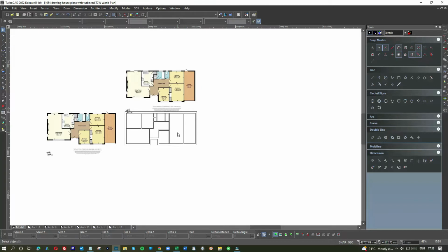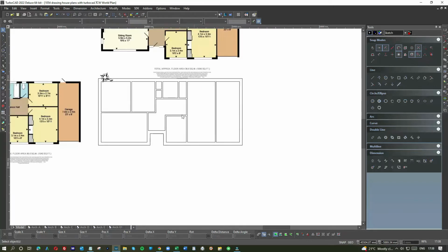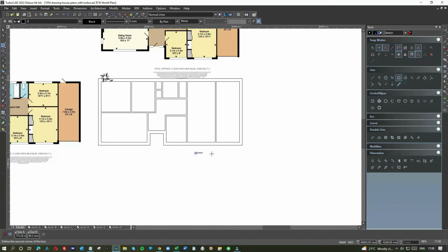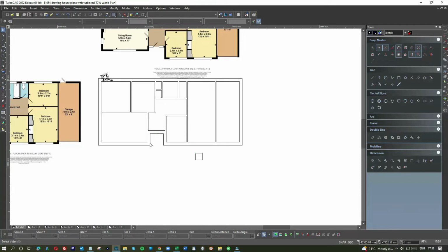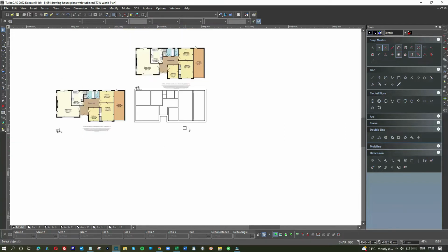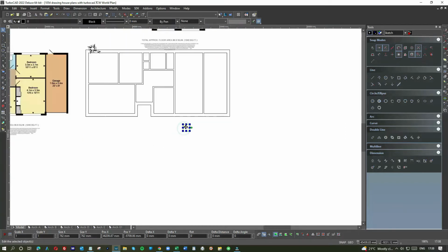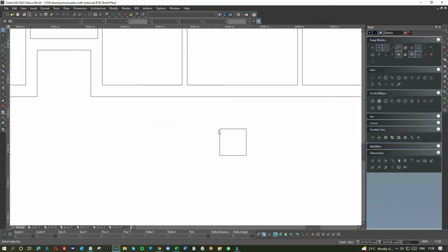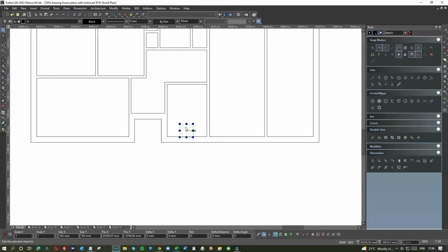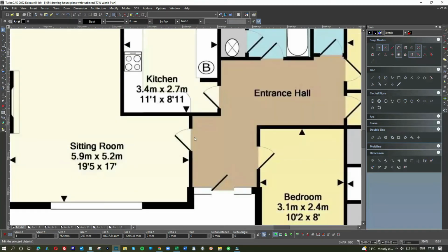So, on projects like this, what I do is I'm going to get a little box. I'm going to do tab 762. Tab 762. Now 762 is the standard door size. So in other words, I'm just going to look now at the drawings, and I'm going to use the modify tools to cut my door openings. And the doors may not be in exactly the same place, but with the way they've done it there, I would never put a door in the middle of the room like that, and I certainly wouldn't put it leaning this way.